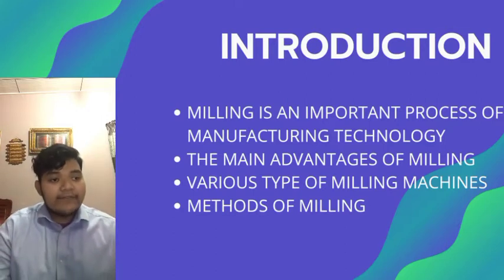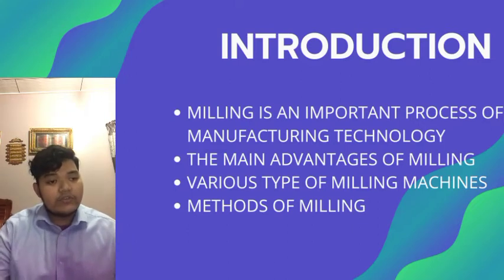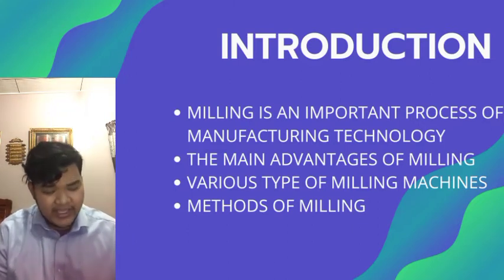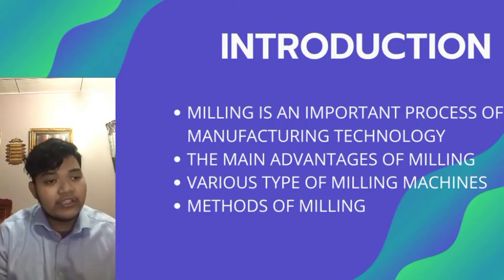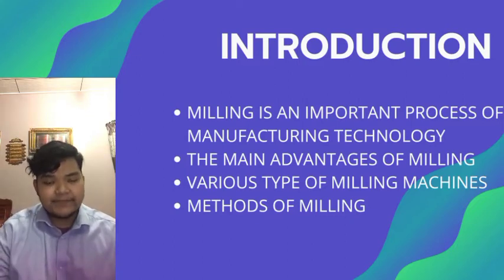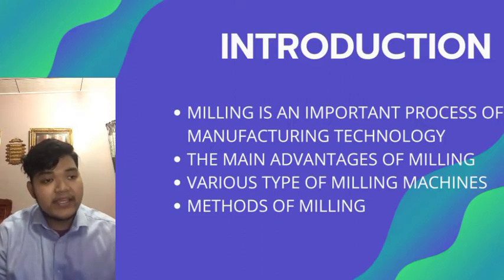There are a few methods of milling. The first method is single piece milling. This method is used for milling a single job work which is held on the milling machine. It is important to note that the piece has to be worked in a single machine cycle for it to be classified under this category of milling methods. The next one is string milling, quite similar to single piece milling, the only difference being that instead of a single piece, there are several parts which are simultaneously fixed and worked upon.